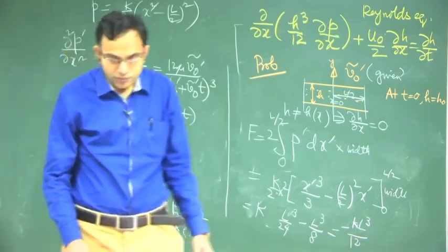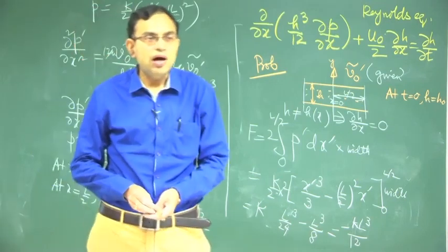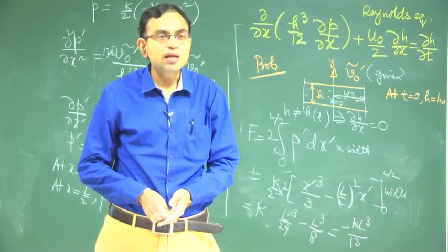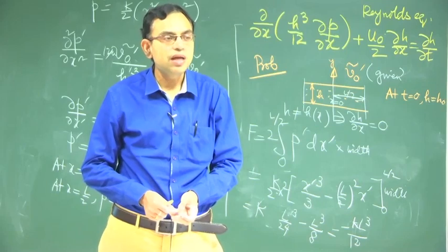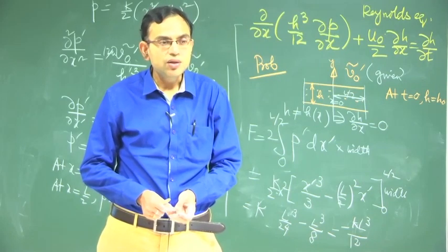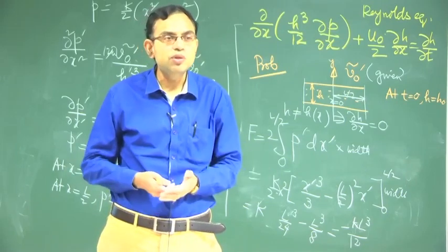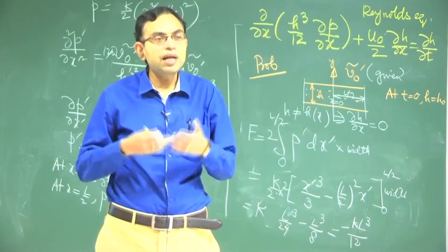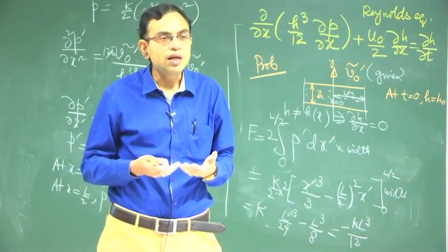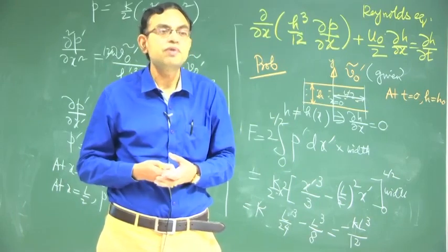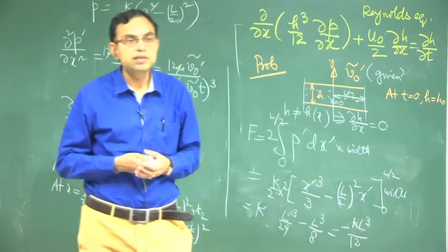Okay. So, we have discussed significantly about the lubrication theory and we have understood how pressure gets distributed in a system which is confined, but the confinement height can be a function of x and time. So far we have considered that the force that is acting is because of pressure distribution or shear, but there are many interesting problems in micro scale where the pressure distribution itself is generated because of the remarkable physics of surface tension, and from the next lecture we will start understanding how surface tension plays its role in microfluidics.